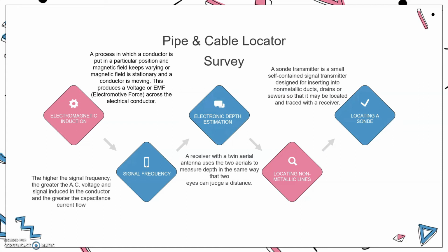As a sonde is approached with a horizontal aerial, it will detect a rising signal as it comes within range. That will then fall to null again, giving the illusion that the peak signal has been passed over the sonde. But if the traverse continues, the signal will rise to a much higher point again, the height of which shows the sonde's real and exact location. It will then fall to null again, followed by a small rise and then fade away.